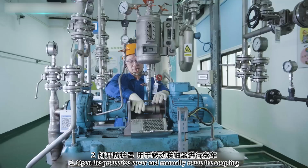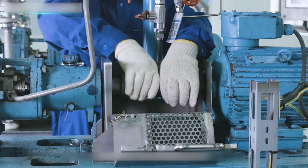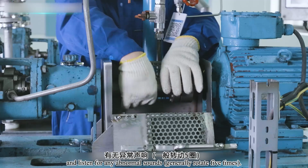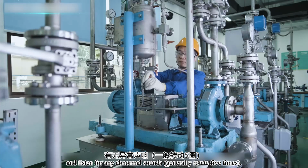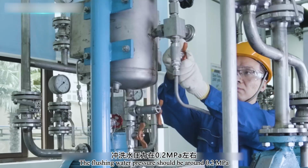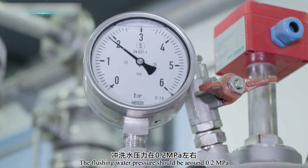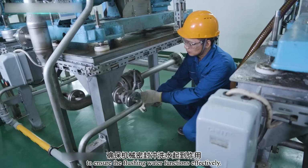Second, open the protective cover and manually rotate the coupling to check if the rotation is smooth and uniform, and listen for any abnormal sounds. Generally, rotate 5 times. Third, open the mechanical seal flushing water valve. The flushing water pressure should be around 0.2 megapascal to ensure the flushing water functions effectively.